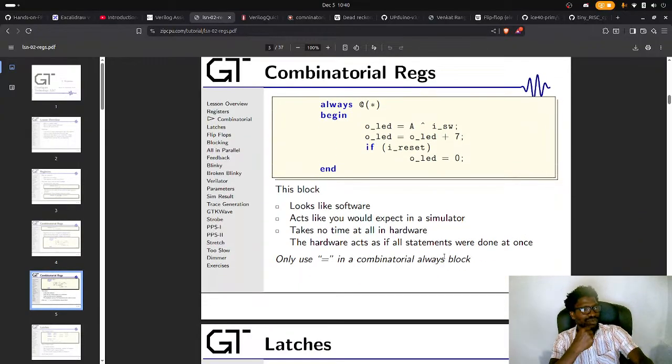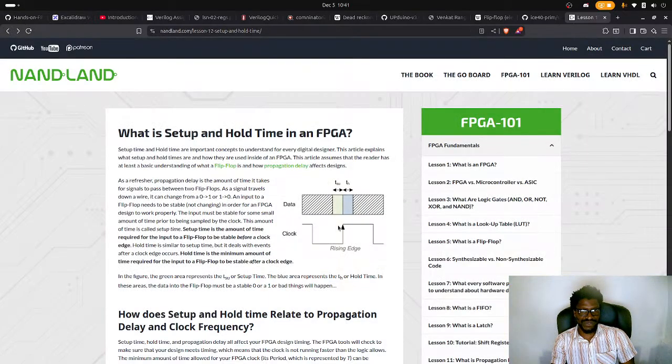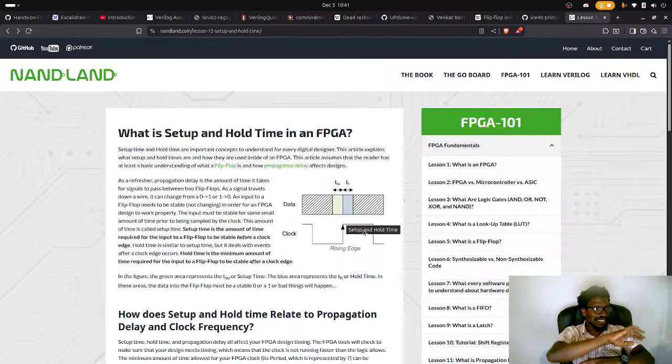This is when you'll be able to get this data. So basically what happens is that you run an operation on this rising edge, and then during this stable edge, or during this stable edge if you did it on a falling edge, data is now propagated between all the registers and